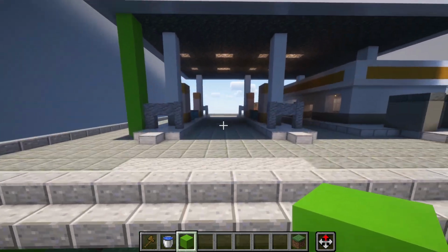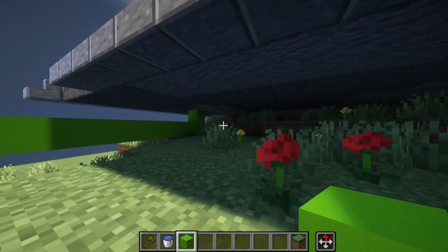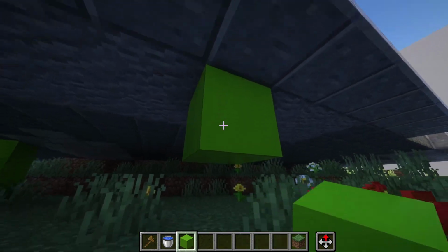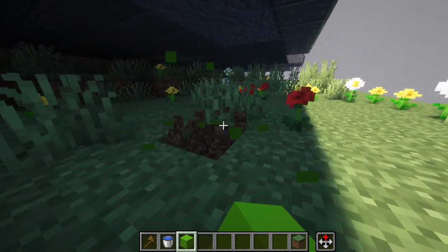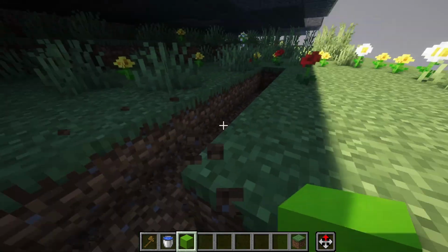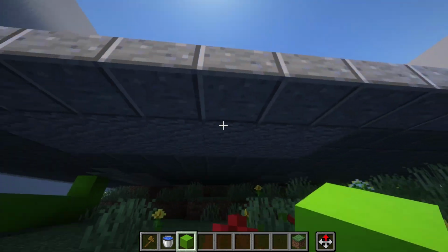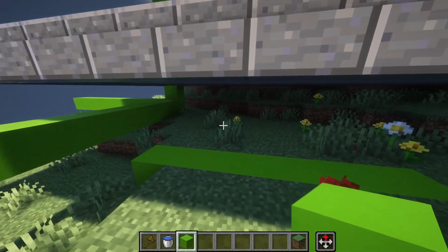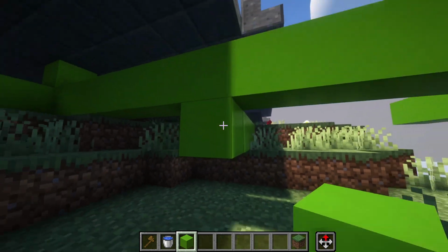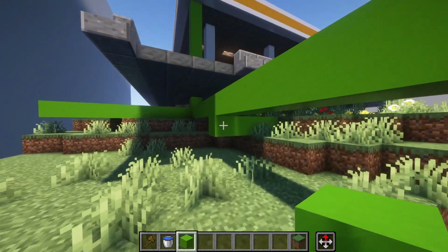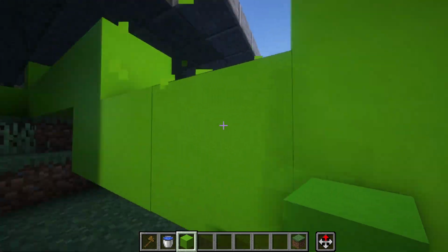It will permeate most of the water that it can into the soil or the mediums beneath, but eventually, over time, that will become oversaturated and an underlying drainage pipe, usually a perforated plastic pipe, will be beneath the permeable surfaces and capture any of the excess flow, and then, you've guessed it, connects back into the system, which, since water can't travel uphill, will probably be down here.